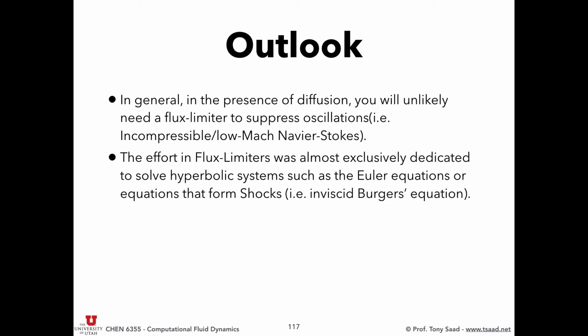So by all means, when you go in that direction, your bread and butter are going to be flux limiters. If you want to preserve structures and advect them, if you're concerned about vortical structures being shed from a helicopter or a fuselage, by all means use flux limiters and try to preserve all of these vortical structures.